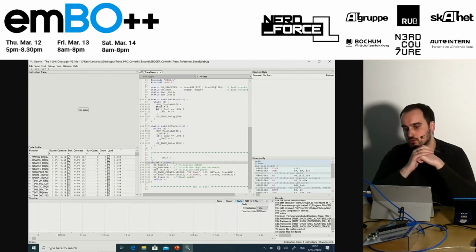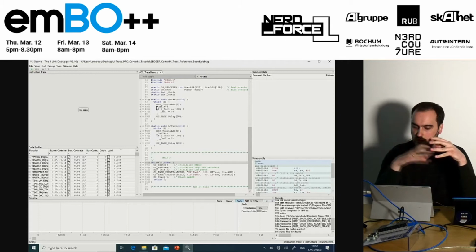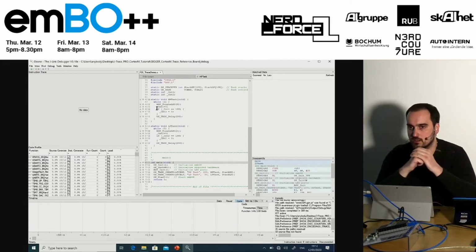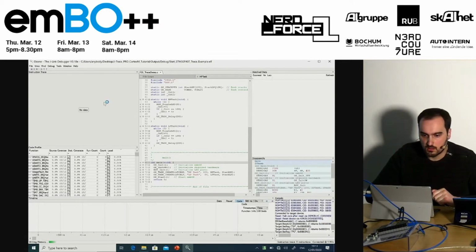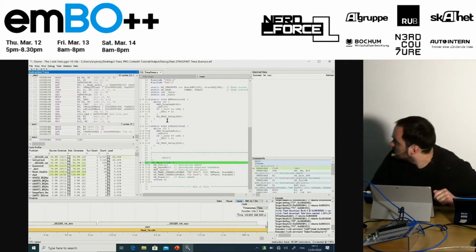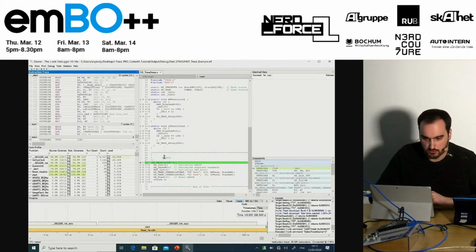To extract this, we use the trace pins. That is another prerequisite. So additionally to the debug pins that you have, which is, for example, JTAG, you also have to implement the trace pins, which are 5 additional pins, so 1 clock, 4 data pins. Yeah, so let's get it up and running. So I loaded the project. I just start the debug session, and we landed up at main, as we're used to.